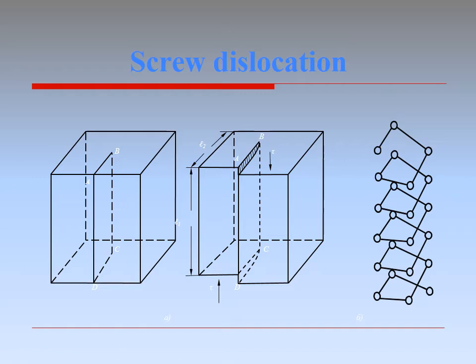This figure shows the arrangement of atoms in two vertical planes passing directly on either side of the shear plane ABCD. The resulting shift of the described area of imperfection is called a screw dislocation. As atoms are in it like a spiral staircase. Screw dislocation, as well as in the screw, can be left and right. They turn to each other as mirror images.